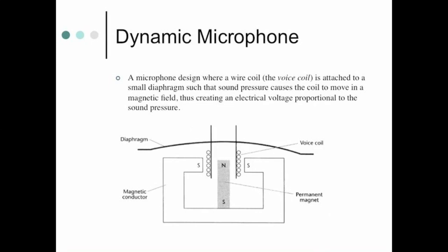You put electricity into the speaker, it goes through the coil, and because there are fixed magnets, it makes the diaphragm move back and forth based upon the fluctuation in magnetic fields. A speaker and a dynamic microphone are very similar in many ways, the opposite of the same principles. And of course, one diaphragm is relatively small in a microphone, one diaphragm is relatively large in a speaker.